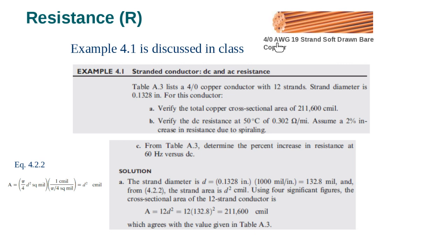So that's just to show you what we mean by stranded conductor. We call it a stranded conductor, so it's made of strands. And this is also to reduce the skin effect. Part of the purpose is to reduce the skin effect instead of a solid conductor. Therefore, the current will flow on all these strands to make them smooth. So all the transmission lines are like this. Okay, strand. Let us look at the example here.